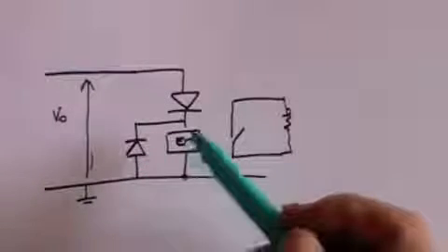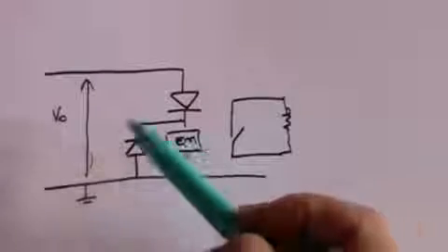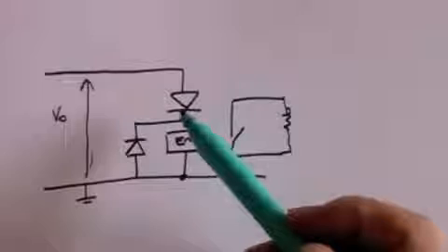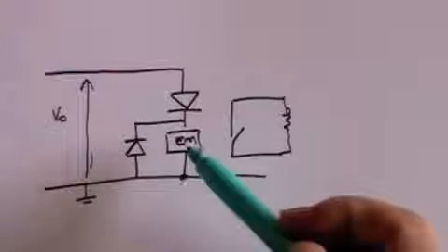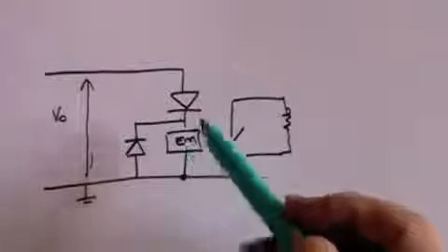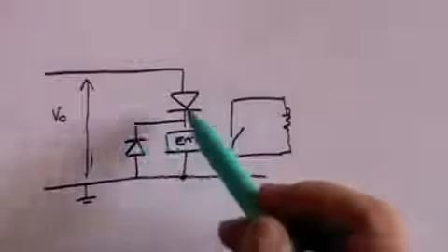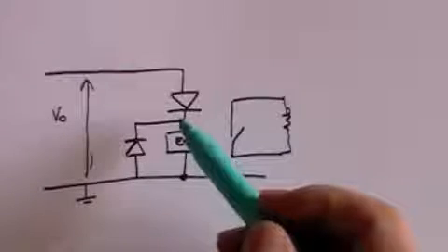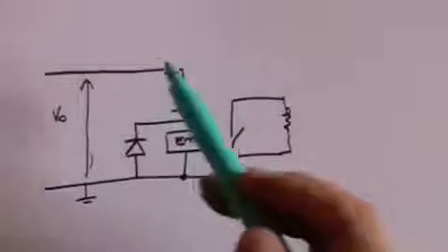What's the reason for that diode? Well, when it gets light again the following morning, this voltage is going to flip to become negative again and the current will stop flowing. The electromagnet will stop, but there is often what's called a back EMF, which can damage the circuitry. And so what this diode does is it allows that electromagnet to discharge without causing any trouble to the operational amplifier back here.